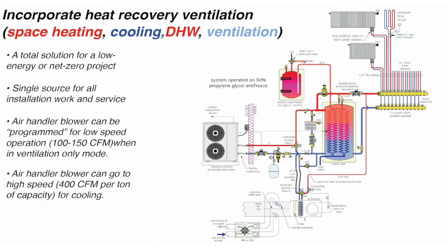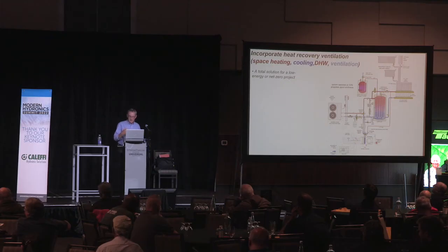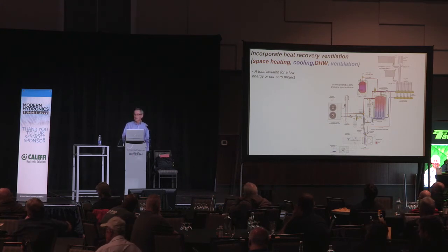It's a radiator valve with a capillary tube, or I guess you say capillary tube up here, right? It's one of the Canadian words I learned many years ago from Robert Bean, capillary tube. It's a capillary tube control that simply monitors that discharge air temperature. So when it needs a little heat input, it trickles some of that warm water from the buffer tank through that coil. It's another feature beyond what a standard HRV can do. It's a comfort-enhancing feature, okay?